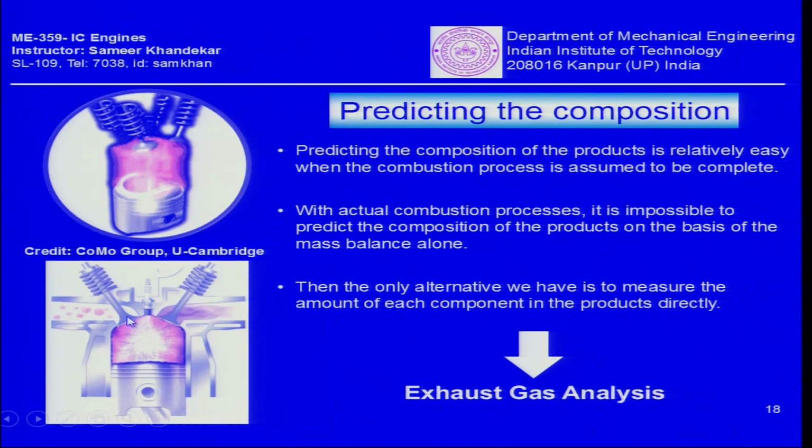How much time was available for the inlet valve to open and close, what is the temperature distribution, what is the cooling close to the cylinder liner, what is the type of cooling provided to the piston, are there leakages occurring because of which the pressure and temperature are not proper, how is the flame getting spread from the spark plug in the entire combustion chamber, what is the clearance volume, what type of mixture, how much air and fuel came inside the system from the inlet valve. All these are very, very important parameters which will determine what type of exhaust will come out